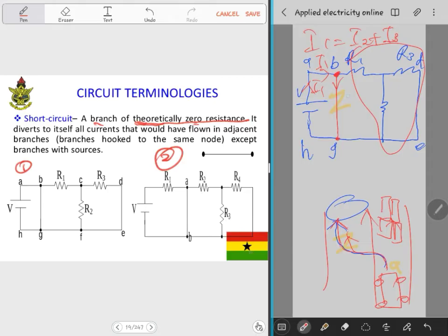So that's the same thing. That's why we'll have an I1 here. The same thing will come here. So it flows from this part here, and comes back. This is the same I1 and comes back to the voltage source, negative side, positive side. Then again, be very familiar with this. For a voltage source, the long bar is the positive side and the short bar is the negative side. It will help a lot later.